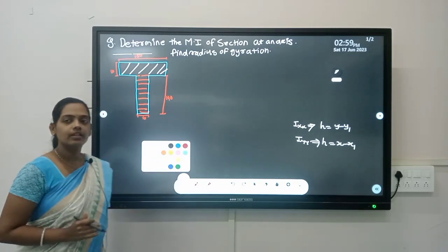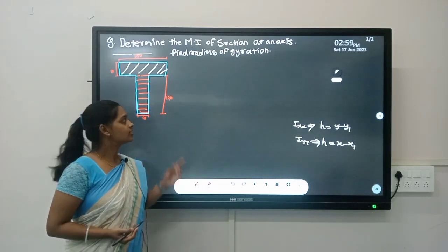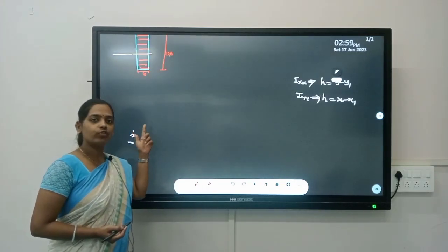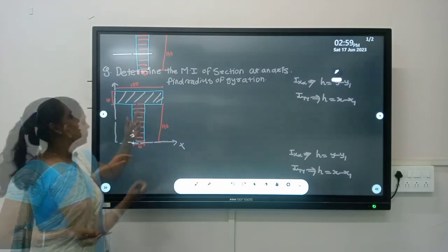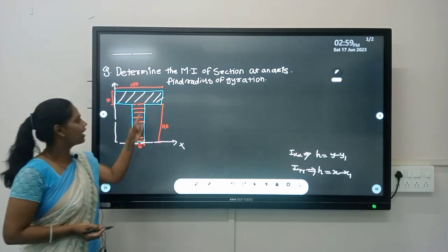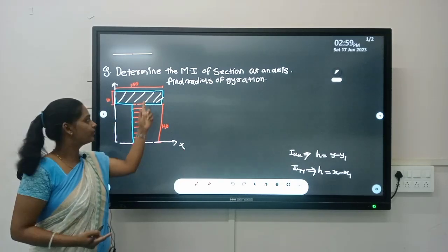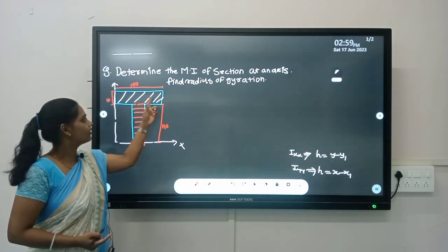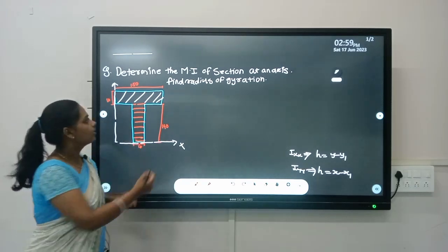The first step to calculate moment of inertia, just put the given figure into first quadrant. For that, we will have the leftmost part as y-axis and bottommost part as x-axis. Then we have already bifurcated the given figure into two components. Okay, first rectangle and second rectangle.